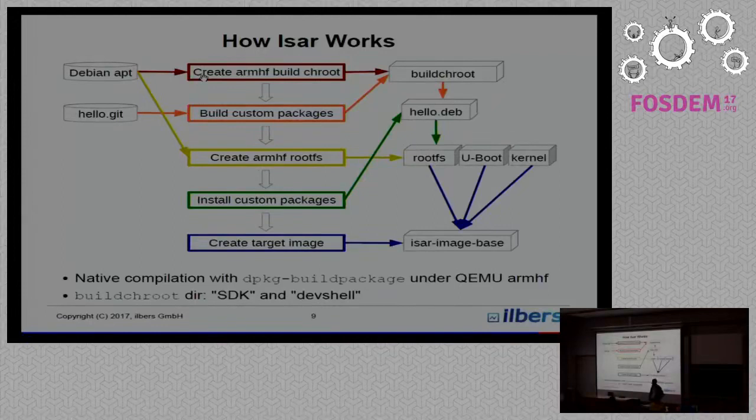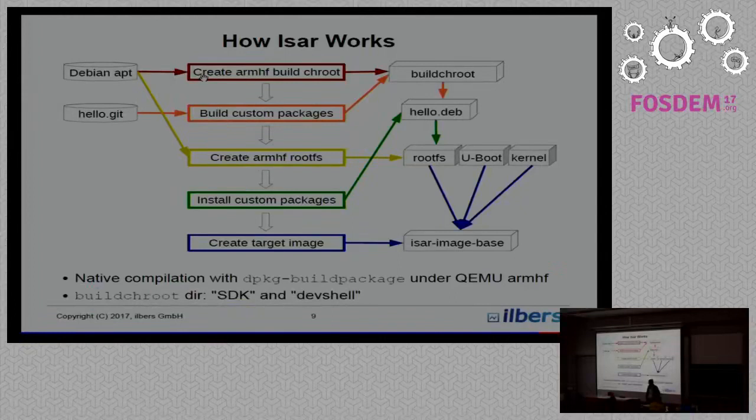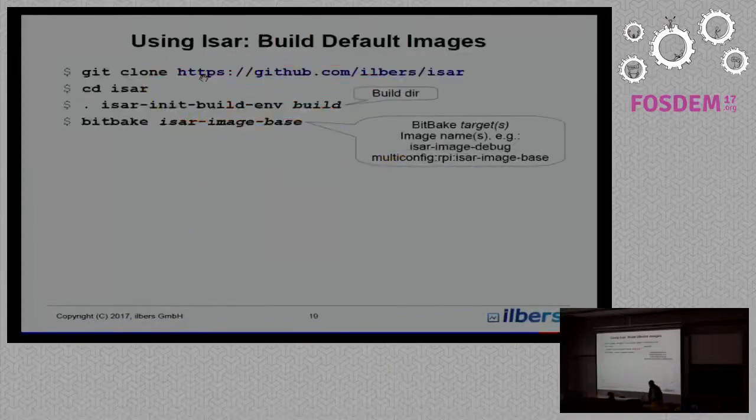and build the packages with the standard dpkg-buildpackage toolset. After all packages are built, we call multistrap again to create a root file system. Then we install the packages that we built there and create a bootable, complete firmware image containing also U-boot, kernel, and rootfs. So these are simple 5 steps, and they are all incorporated in one command, like we know from Yocto.